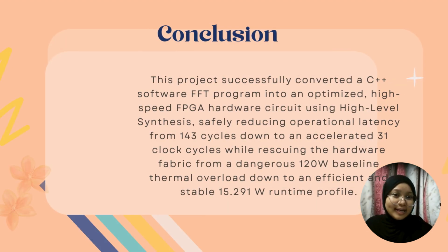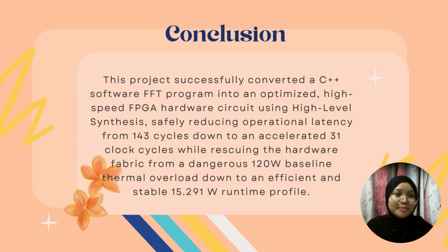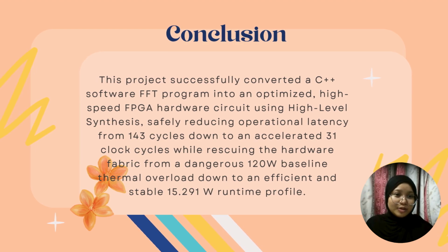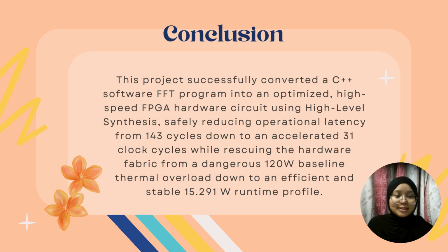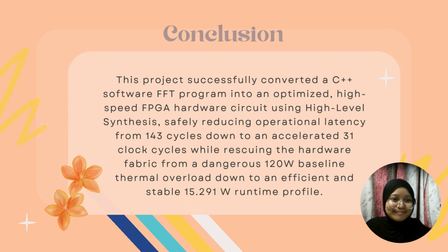For the conclusion, this project successfully converted a C++ software FFT program into an optimized high-speed FPGA hardware circuit using high-level synthesis, safely reducing operational latency from 143 cycles down to an accelerated 31 clock cycles, while rescuing the hardware fabric from a dangerous 120-watt baseline thermal overload down to an efficient and stable 15.291 watt runtime profile. That's all from us.